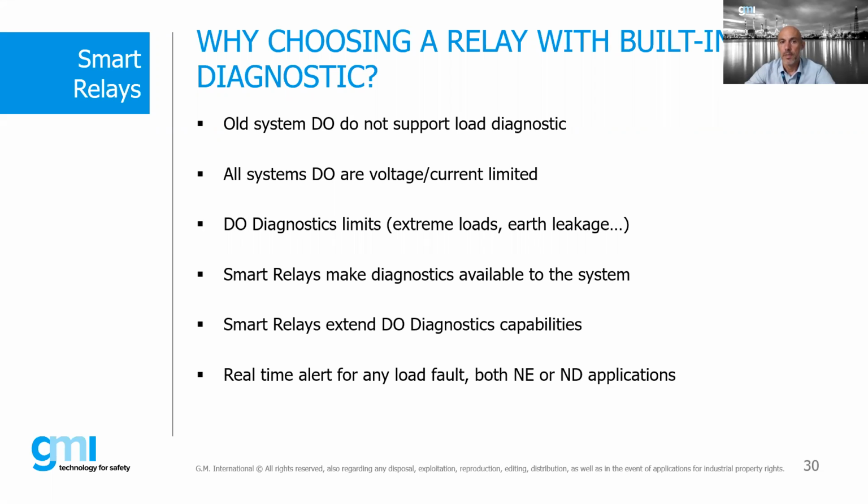First, not all digital output cards support diagnostic. They just close and open the contact. They do not know what happens on the load part. All DO systems are voltage and current limited, so they are not able to power the load, or maybe the DO diagnostic limits some extreme load leakage. They cannot detect those kinds of failure.